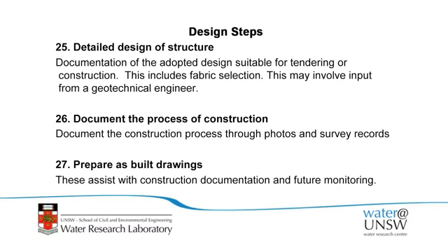So the better you document it, the more watertight it is if something goes wrong down the track, or if it's damaged and the damage exceeds what it was designed for, versus an argument about whether it wasn't built to design, or whether it's simply that the conditions exceeded what it was designed for. So similarly, prepare as-built drawings. I'd always recommend that. They assist with documentation and with future monitoring as well.